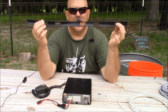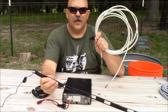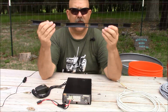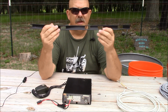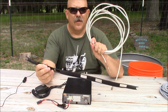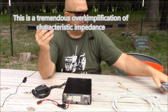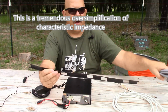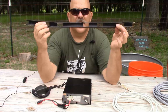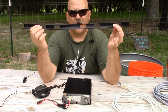The thing we need to keep in mind when we're using a balanced feeder instead of using coaxial cable is what's known as characteristic impedance. We already know that the output of our radio is looking for a 50 ohm load, and that radio coax provides that pretty perfect match. And then we have TV coax, which is pretty doggone close. And then we have something like this, which is 450 ohms of characteristic impedance.